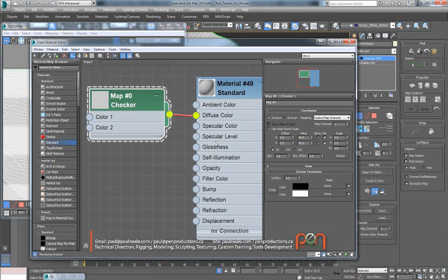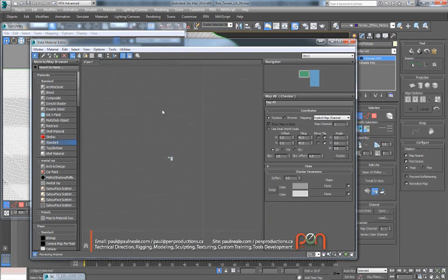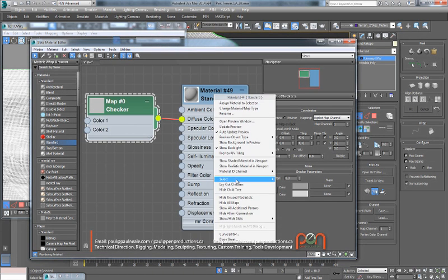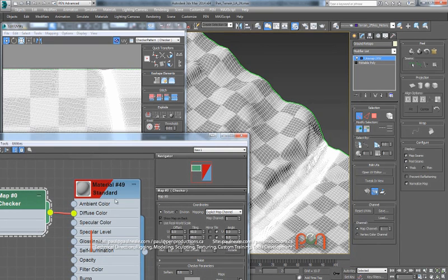We'll see how that does. And set our colors, just so we can see everything better, to a couple of mid-tone grays. Now a little bit darker. There we go. And let's right click on that and say show realistic, or you can say show shaded. Should do it. And so now we have smaller checkerboard patterns that we can see. Let's increase the size to 80.